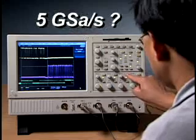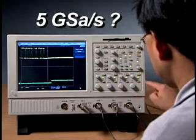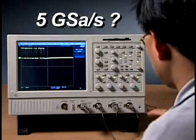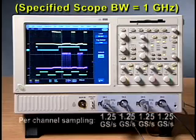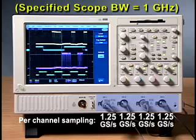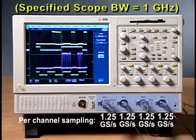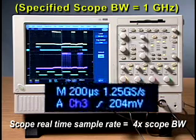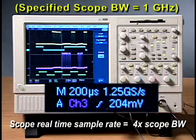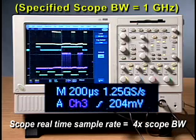While the banner spec of an oscilloscope may promise this maximized sample rate, it will only apply that sample rate to 1 channel. If you're in the market for a 4-channel scope, you'll naturally want access to full bandwidth on more than 1 channel. The sample rate of the scope you choose should be 4 times greater than the scope's bandwidth for capturing the high-frequency components of the signal being displayed. This particular scope only has a real-time bandwidth of 300 MHz with its 1.25 gigasample sample rate.